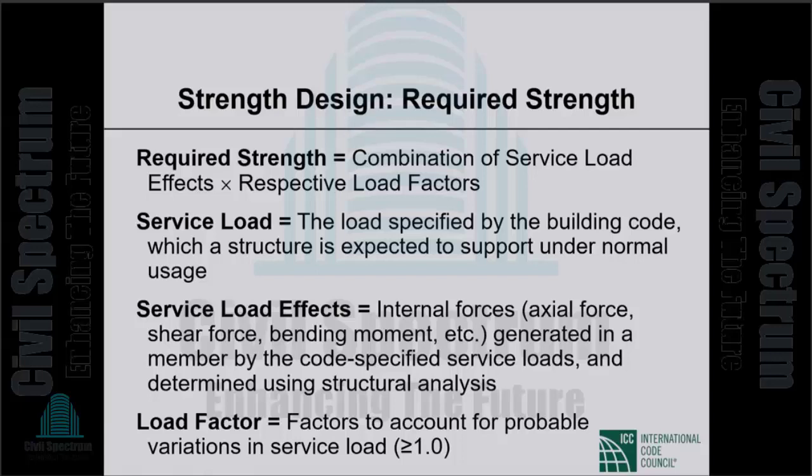We analyze our structure elastically under the service loads. We calculate bending moments, shear forces, axial forces in our structural members. Those are internal forces caused by the external loads. Those are also called load effects. Okay, so there are loads and load effects: the externally applied loads and the internal forces caused by the externally applied loads. The load effects are amplified by load factors to account for probable variations in service loads.